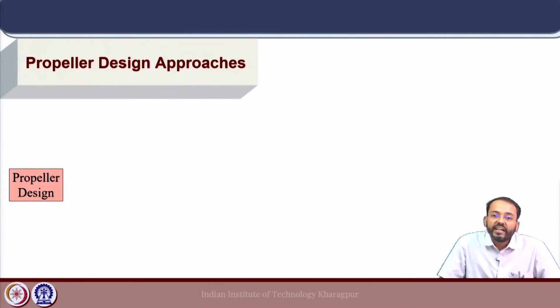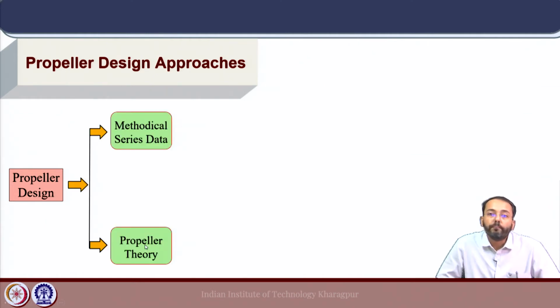Now, if we look into the different design approaches for marine propellers, there are two basic approaches which have been used extensively for propeller design. The first is the methodical series based approach, where the methodical series data for different types of propellers are used to obtain a basic design, and the second design approach is to use the propeller theory, that means mainly circulation theory, to develop the blade design at different radial locations and then the entire blade geometry.